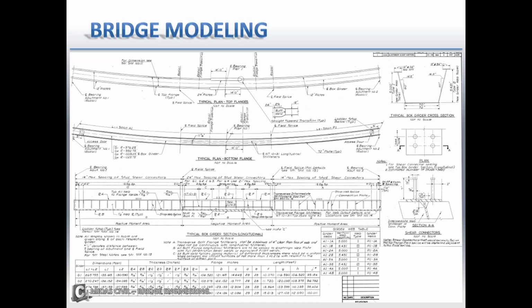So yeah, you're going to want to know all of the distances separately, and basically each girder is going to be split into different sections because Midas doesn't let you create one huge girder with different thicknesses and widths all along. So what we'll do is make a bunch of different girders and join them into one.